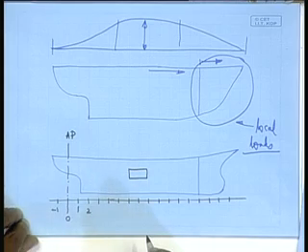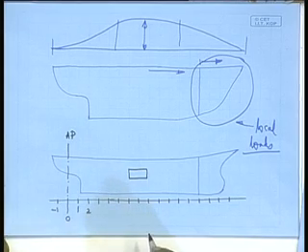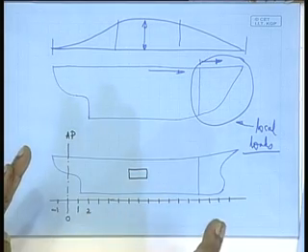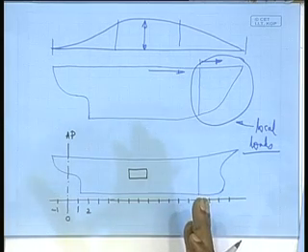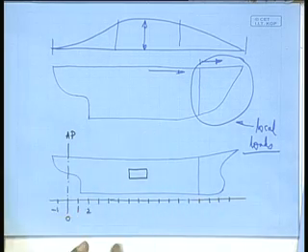Well, so frame spacing plays an important role as far as giving the references. Second important role is spacing of stiffener. So I can have it small, I can have it big. Spacing can be 500 millimeter, spacing can be 1000 millimeter. So what spacing I will take will again depend on your structural design, what you are carrying out. If you choose 500, it will give you something. If you choose 600, something else, and so on and so forth.